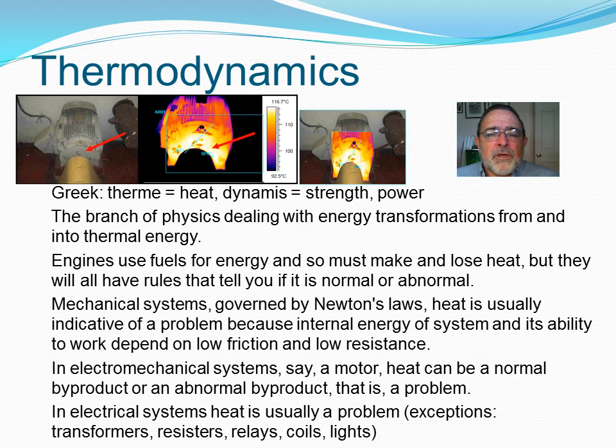Here are 3 images of the same motor. Left to right, this is what we call a real-time or an actual visual image using visual light range. The infrared thermograph that is used in the report, and then a picture-in-picture image of the same device. And the picture-in-picture allows you to see in context what the problem is and exactly where the issue is. It focuses your attention, much like the red arrows would for the technician that goes back to repair these.